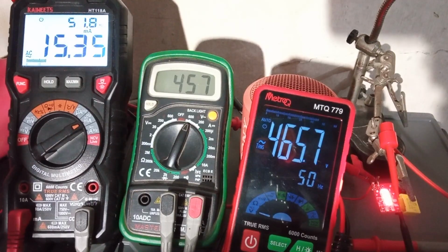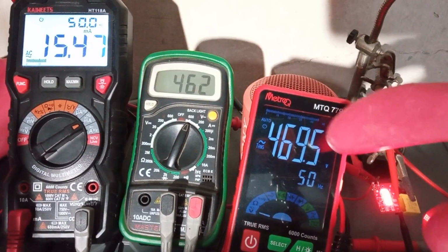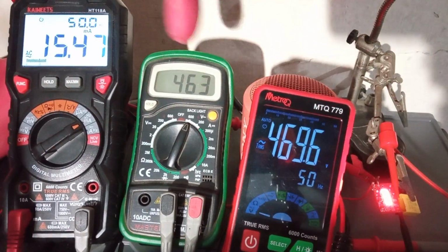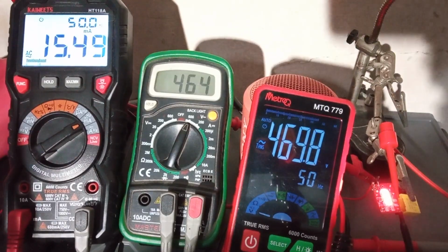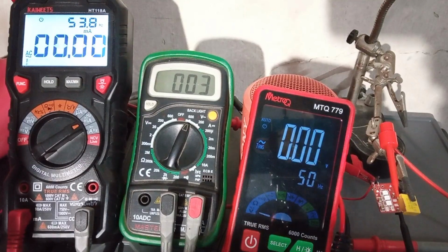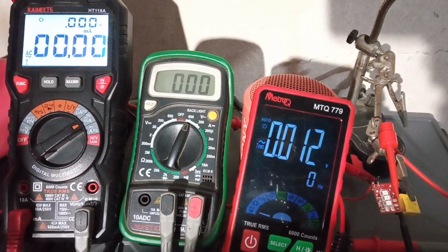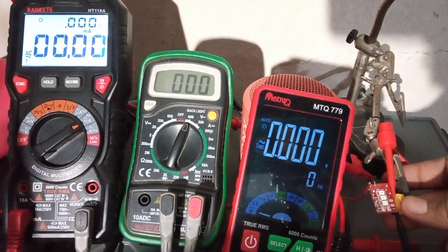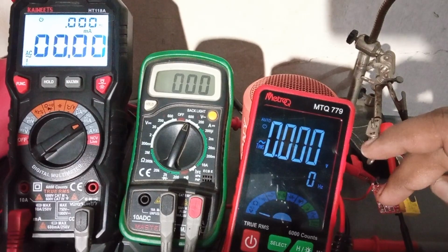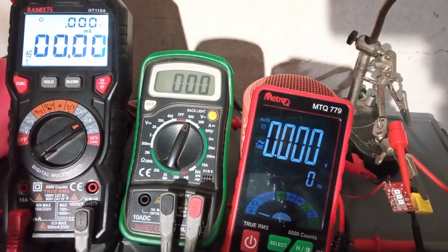So let's increase that to 460 volts. And we can see that we are around 470 right now, and the capacitor is dropping most of that. We are drawing around 15.48 milliamp of current, and the LEDs glow perfectly well. So at this point, if I turn off the circuit and reduce the voltage, so if it's accidentally turned on, it will be pretty safe. And now if I touch something, nothing is actually hot here. So the full wave bridge rectifier, the resistors, nothing is hot.